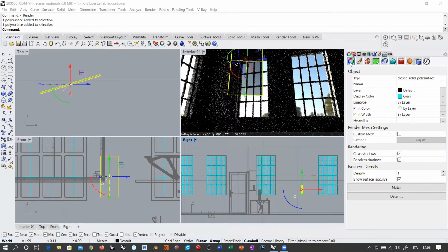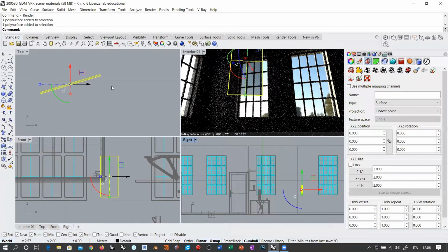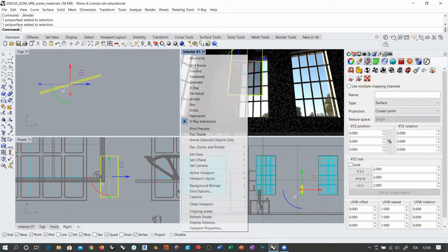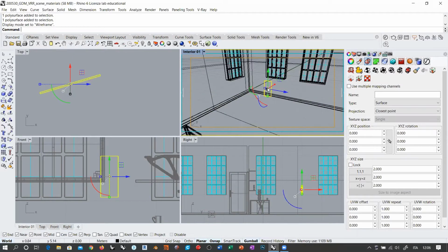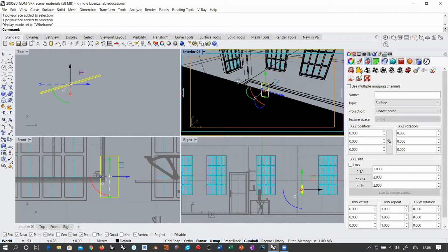I go into the object property, texture mapping, what type of texture mapping I will apply to this. The only texture that I need to map on this are the fingerprints. So I need the fingerprints to be aligned to this face. And then also a standard planar mapping would work. So I would switch to wireframe, take a look at these in a better representation.